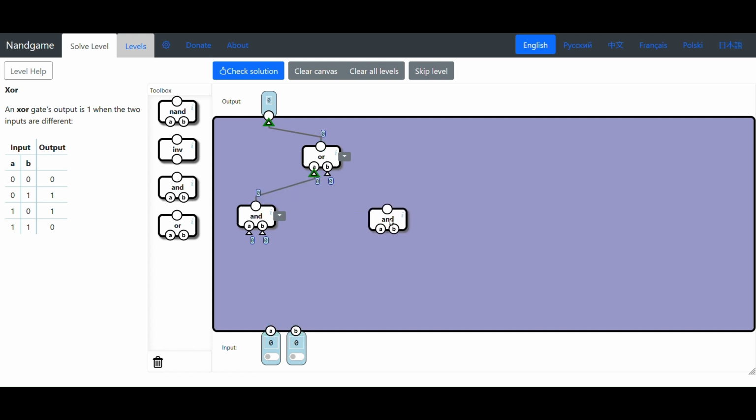We can take these conditions and give their corresponding gates here. So you have a condition where A is off and B is on. So let's put B on here. And let's invert A so that when A is off, one of these is on. So if A is on and B is on, that won't work. But if B is on and A is off, that satisfies this condition here. So that's halfway. Let's just put this over here so we can clear the area a bit.